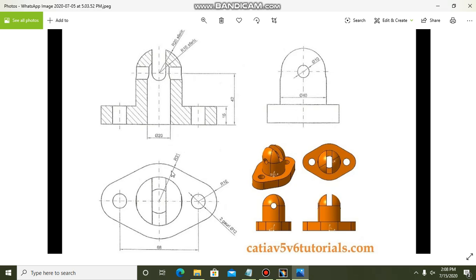Now we have to go for the innermost circle. For example, you can see here the projection, right? We have to project the circle and we have to make an outermost circle. We have 2 more steps yet. The same thing, the circle has to be drawn for diameter 40 and it has to be projected to 42.